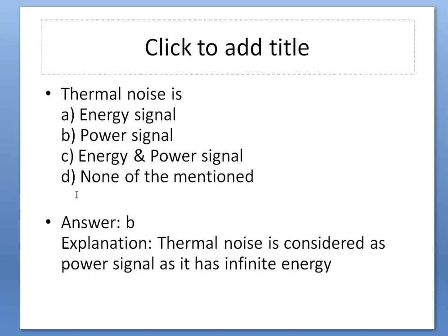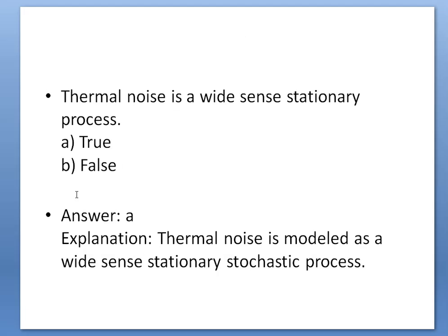It is also infinite energy, but we have to consider thermal noise as a power signal, not an energy signal. Coming to the next bit, thermal noise is a wide sense stationary process. It can be expressed whether it is true or false. Yes, the answer is true. Thermal noise is modeled as a wide sense stationary stochastic process.